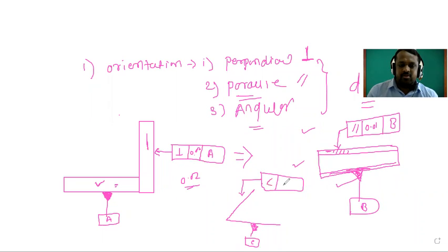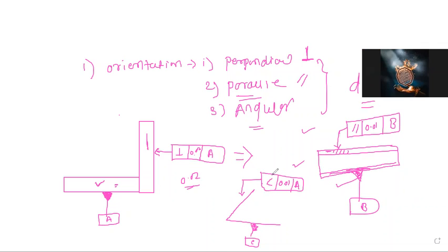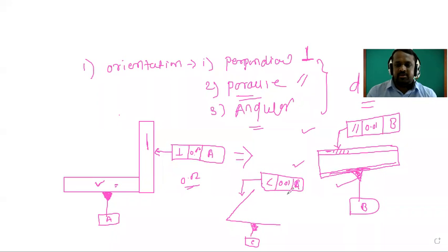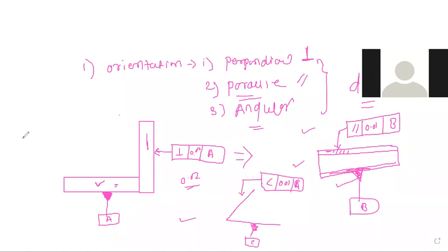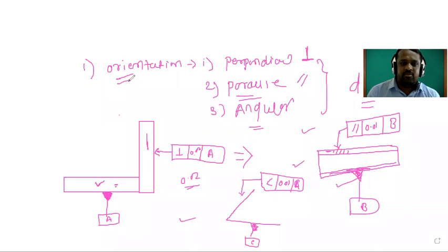This is the symbol for angularity, 0.01 with respect to datum A. The angularity of the plane has a tolerance zone of 0.01 mm to datum plane A. And here you can see this is an orientation feature, so we require the datums.